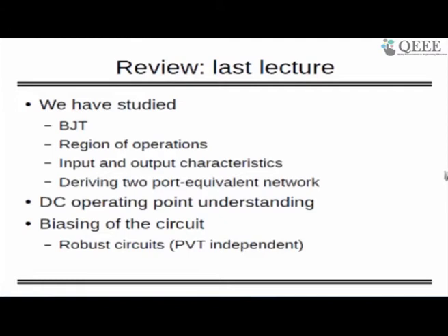Once you do the biasing and everything is done, your next job is to give the input, which is the one you want to get amplified. Now when I connect this input through a function generator, I learned that in the laboratory, most instruments have some input impedance and output impedance. My function generator's output impedance is 50 ohm, and that 50 ohm is actually loading my DC circuit. I was expecting some voltage from the voltage divider of R2 and R1, but instead I am getting something else. So what should I do?